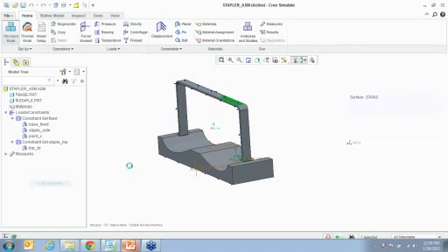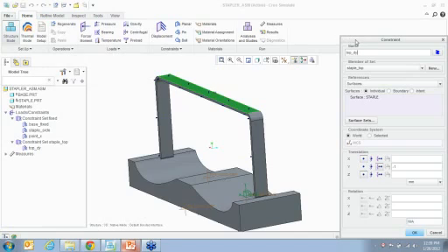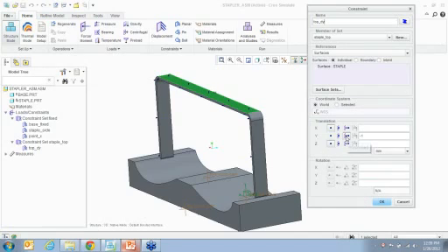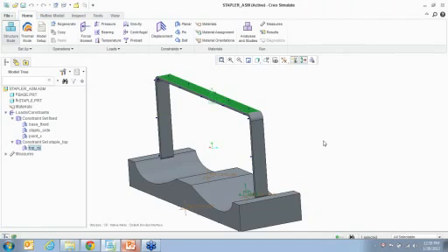I'm putting a constraint at the top. This is another thing that I want to show you. You can use something called a prescribed displacement. So in here, I'm saying it can only move a maximum of -1. So it's going to go down. Okay, that top surface. So that's like a constraint which is going to actually act like a load.